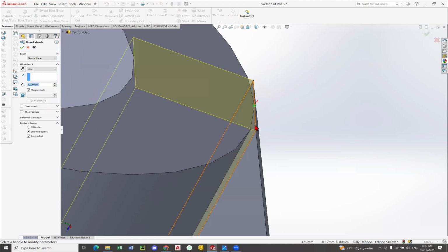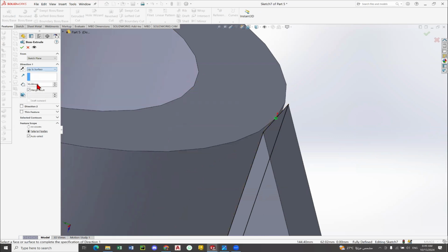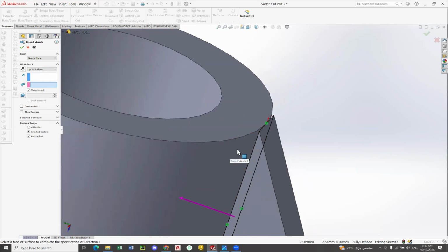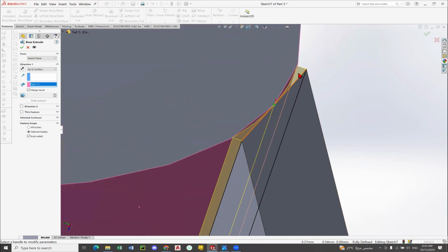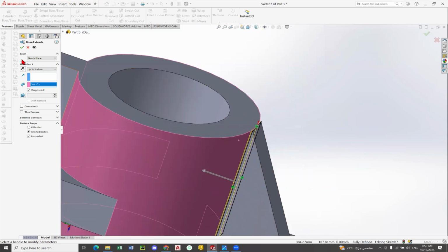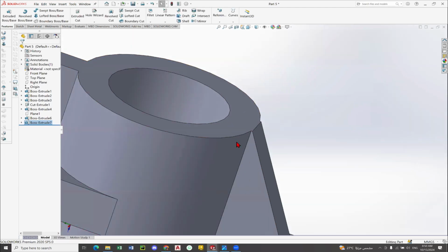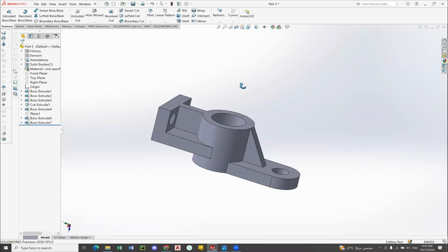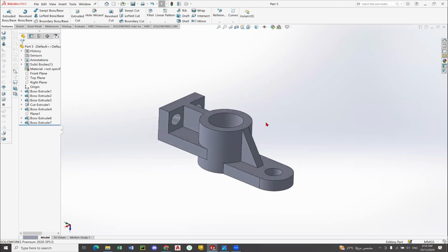And I want to close it, so I want to do extrude up to surface here. Instead of doing it blind, you can choose here up to surface and click this surface there, click it on the circle there, left click on it, like you see here, it has perfectly closed it. Then click OK. Perfectly done and perfectly completed. Like you see out there, then we can click save.